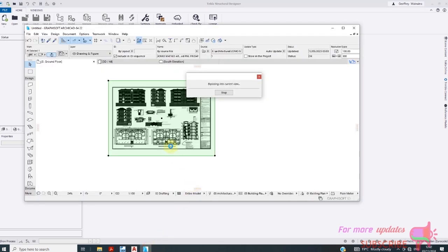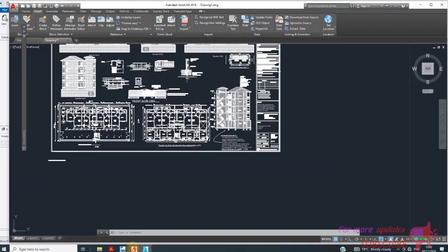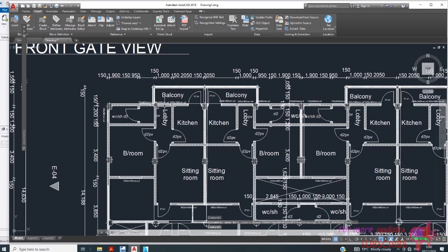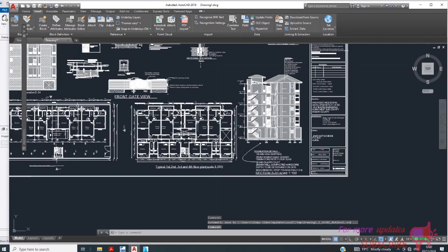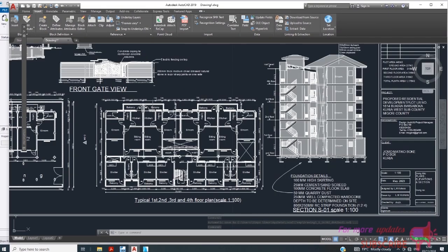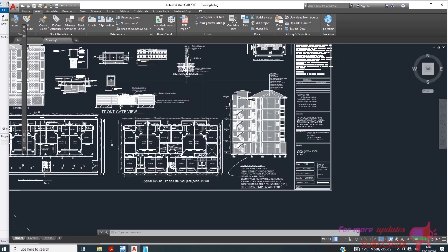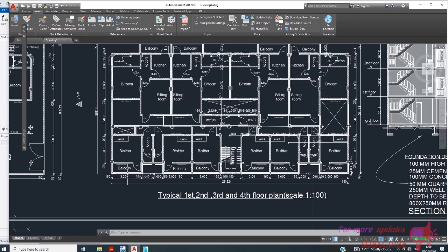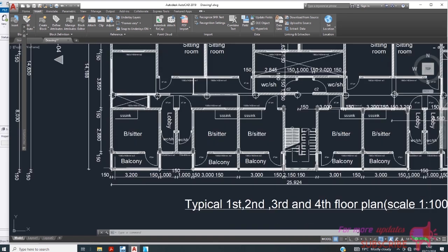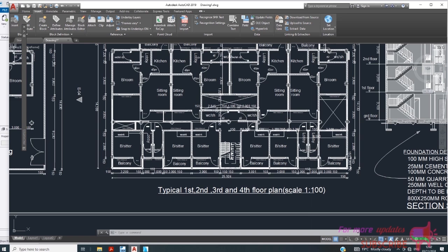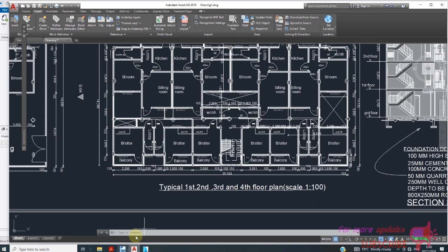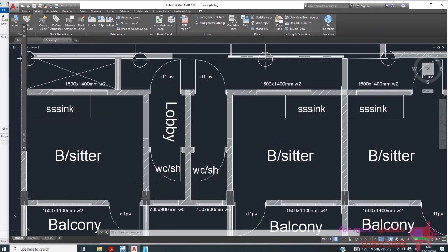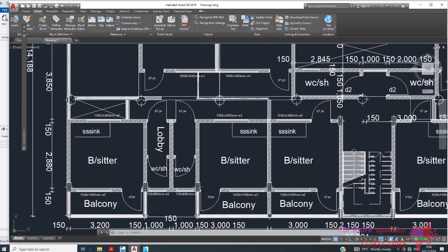I don't want to go correcting these errors one by one, based on the complexity and the size of my building. So I prefer to have all the grid lines that I need so that when I do modeling, I will avoid that error. Having a grid is easier than, for example, in Tekla, when you just want to create a beam where there's no grid.